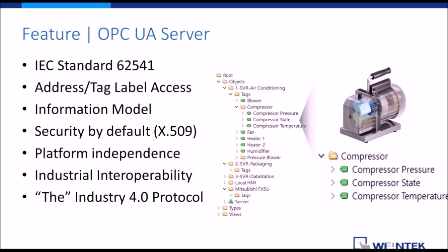So you have to assign different parts of memory for different features. But you have used recent ones like Siemens. Now they are pushing, or I think Omron too, they push for more tag-based PLCs. So for ones who have to access the data from a PLC, they just look at their address space in the case of OPC UA. So it's like a tree type structure, and everything comes in English or your local language, and you immediately know what data it entails. So for IT people, all the details of a tag are contained in the name already. And then there's no real translation from the PLC memory to what it really means.